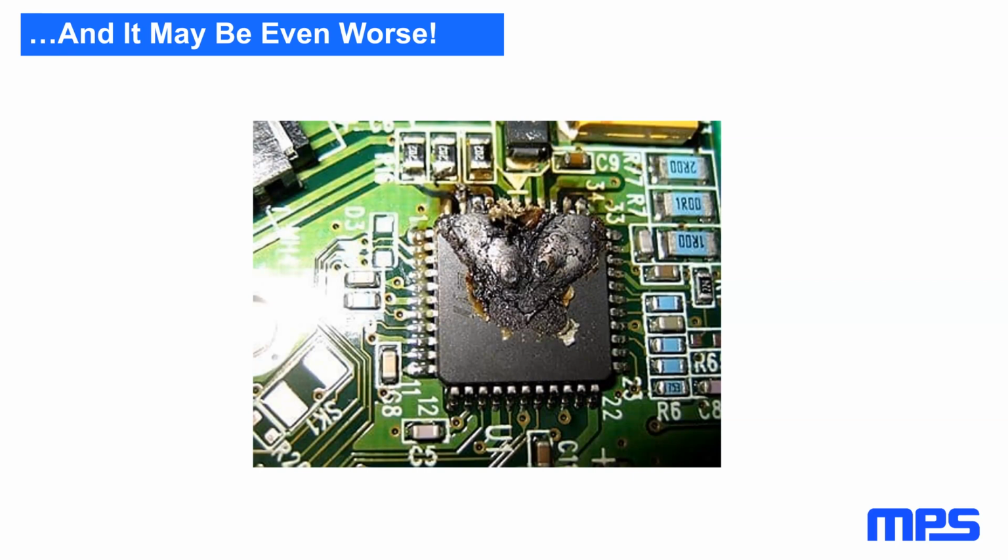One would be to perform all these calculations using worst case numbers, using the maximum RDS(on) at 150 degrees. It's likely that your result will be quite pessimistic. You may come up with half the current that we calculated above, but it would be completely safe. If you're designing a life or death product, it's a prudent thing to do.